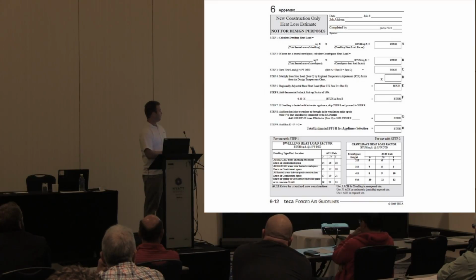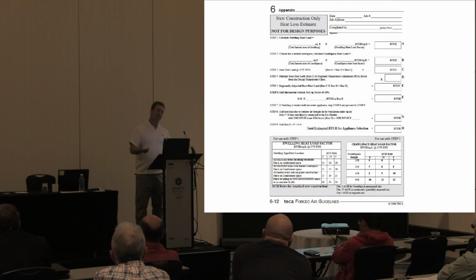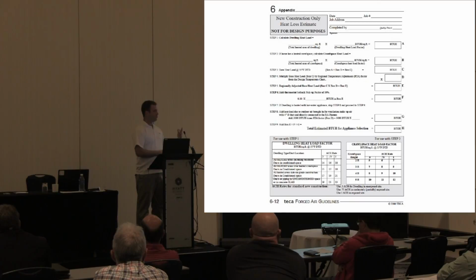And now, if you're going to set the thermostat back, maintaining temperature takes less energy than raising temperature. So if you're putting gas in, you're going to have a setback. You're not going to run it full time all the time. If you have other options, geothermal or heat pump, a lot of people keep it consistent because it doesn't catch up as fast. So we want to make sure we add a 10% buffer on there. We want to oversize the equipment a little bit to make sure we can catch up in the morning in a reasonable amount of time.